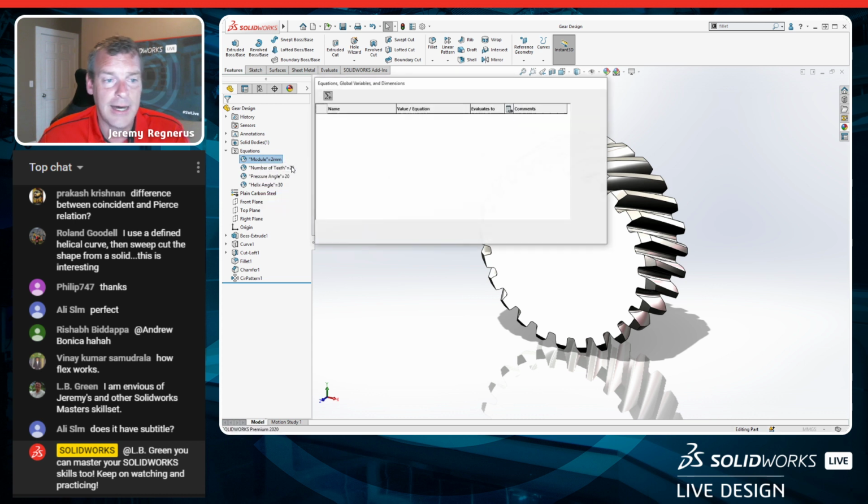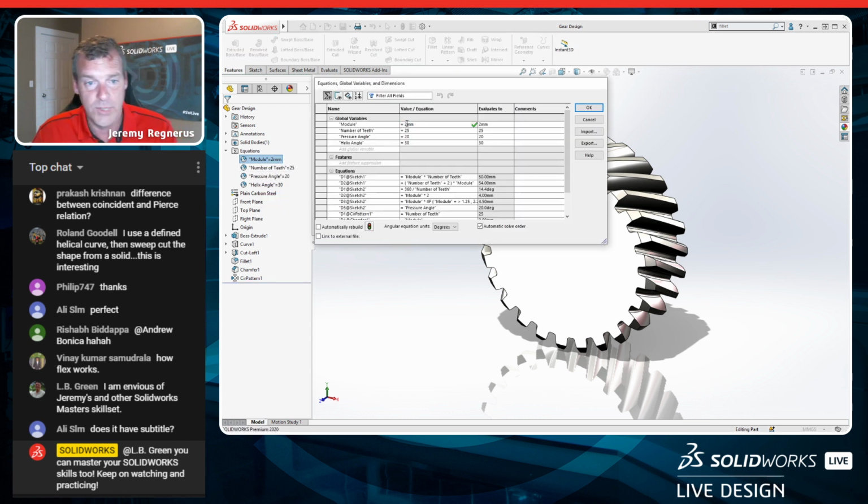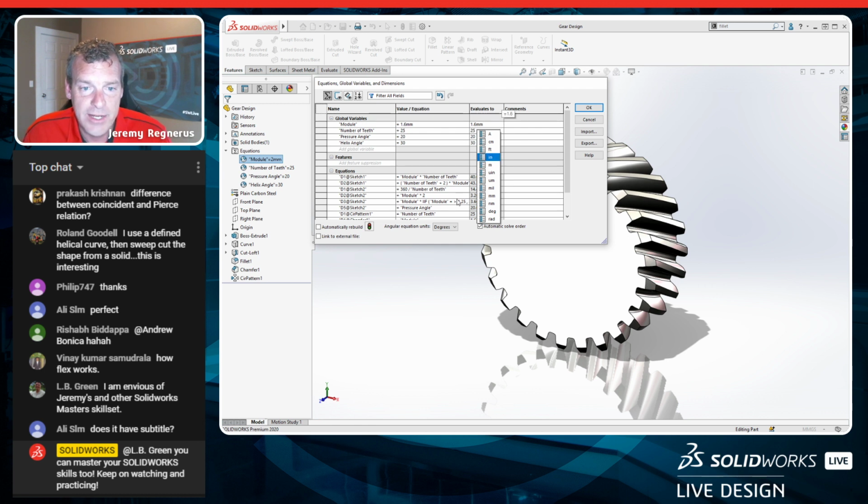I'm going to right click on this value and go to manage equations. What did I just say? I wanted it to be 0.6. Think back to our equation that we made down here, our if-then equation that we did. Because that is now going to be a finer value, that would update, it would change that equation to be a different multiplication value. Our number of teeth, I said I wanted it to be 56.